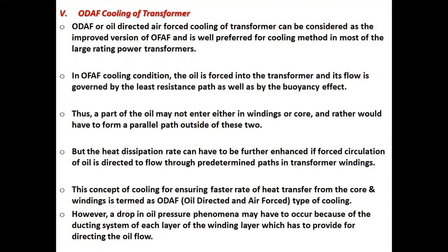In OFAF cooling condition, the oil is forced into the transformer and its flow is governed by the least resistance path as well as by the buoyancy effect. Thus, a part of the oil may not enter either the windings or core and rather would form a parallel path outside of these two.